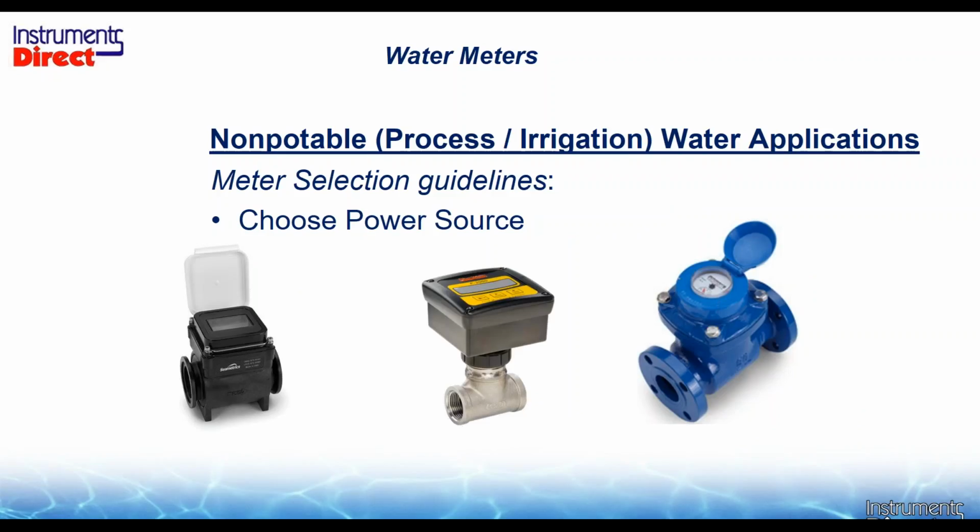Another thing when you get into the non-potable, the process or the irrigation side, especially in the irrigation side, choose your meter based upon its power source. So I'm out in the middle of a cornfield and I'd like to have a mechanical meter with a display, but I don't have any power to retransmit a signal. Okay, so we have a mechanical meter here that requires no power.